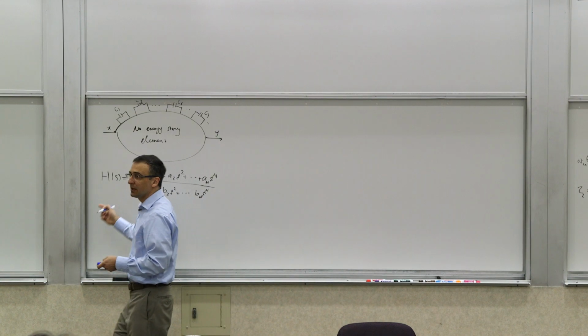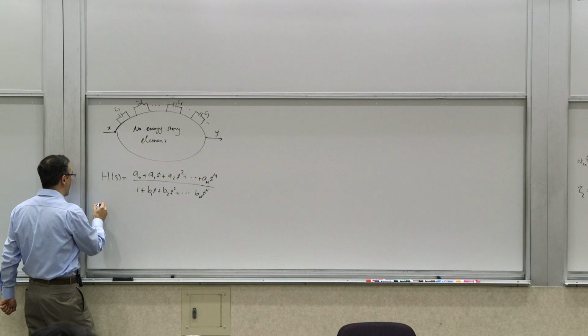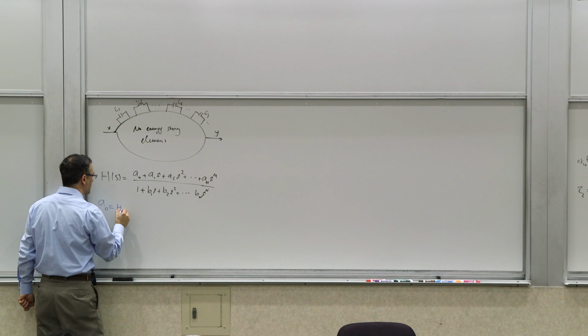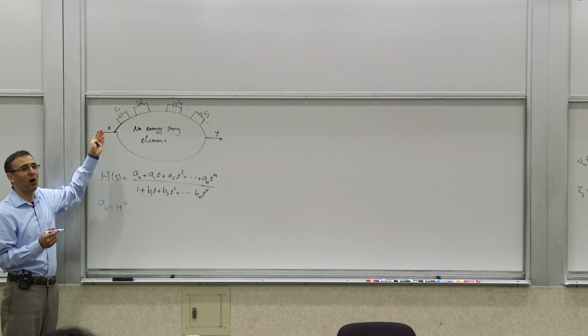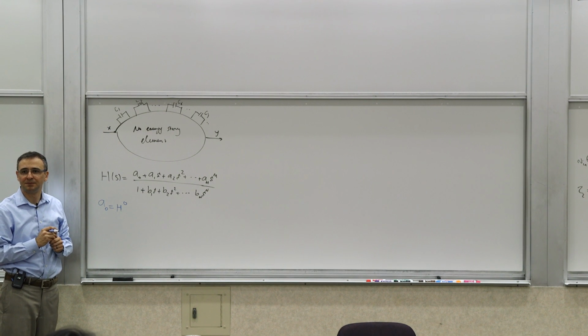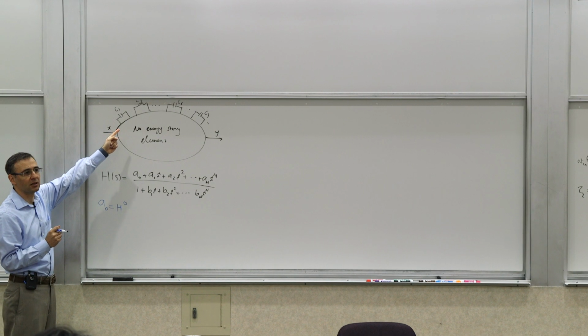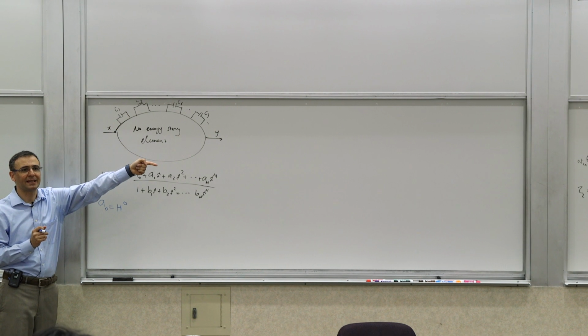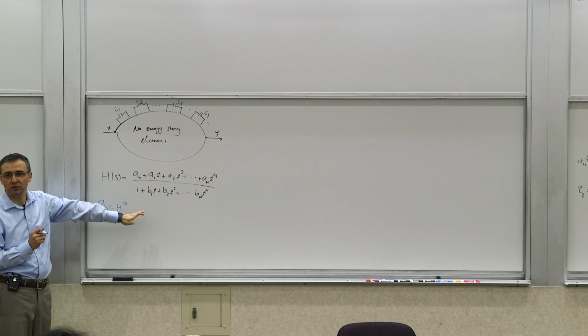Well, a0 is a low-frequency transfer function, right? Which basically is calculated, which say a0 is h0, superscript 0, meaning that it's the transfer function when all the elements are zero valued, right? When you set all the elements, so all the capacitors are open, all the inductors are shorted, you see it's a DC calculation, right? Everything will be a DC calculation, but this was the first one, right?